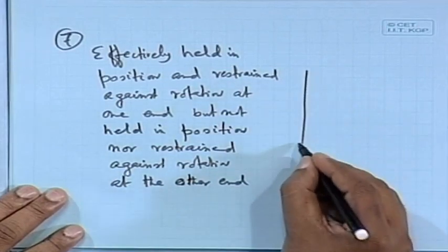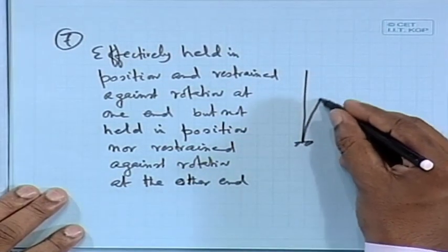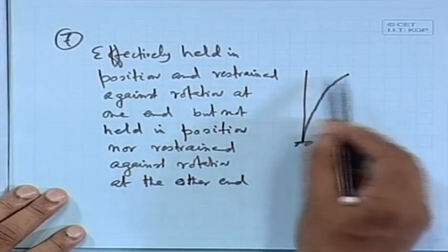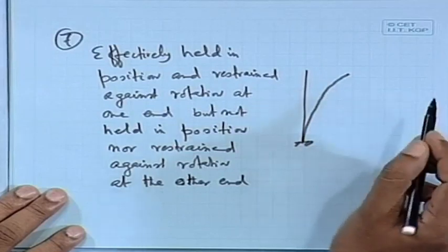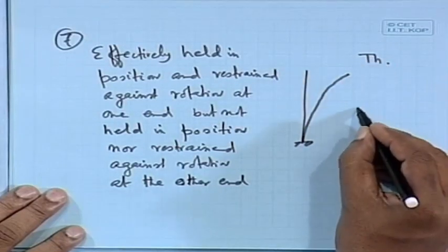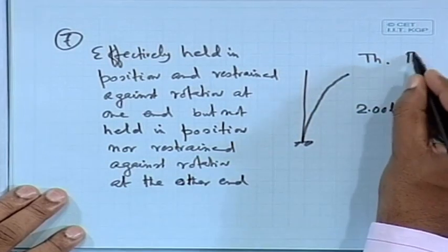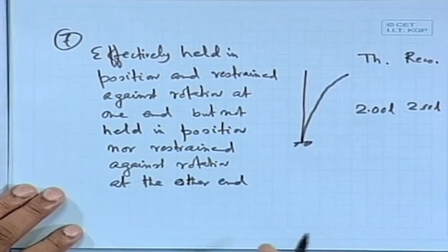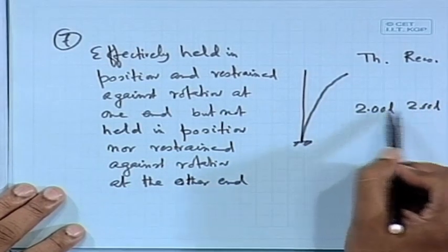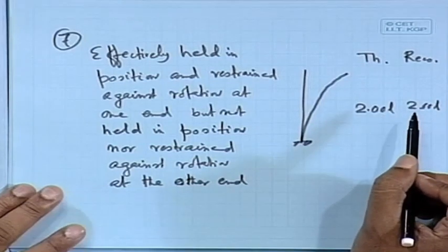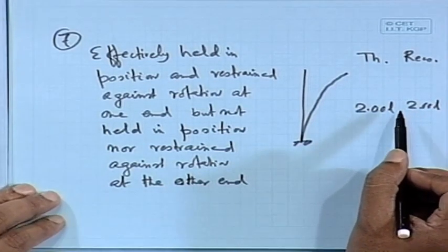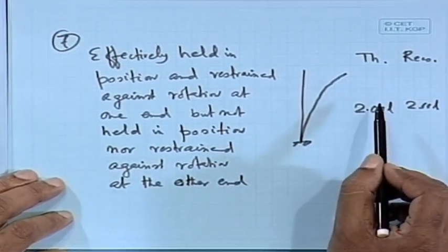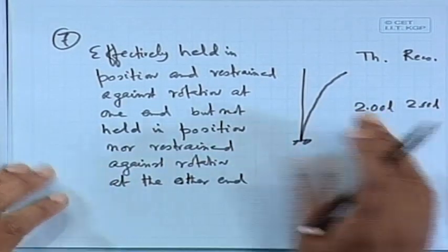So, we are talking like this, as if it goes like this. There is no such limit, neither in movement nor in rotation. The theoretical value gives 2 L, and the recommended value also gives 2 L. This is the maximum we can have, 2 L, that means twice the unsupported length, for the cantilever beam, and the minimum is 0.5 L. So, it is very important what the effective length should be. This is the general case.